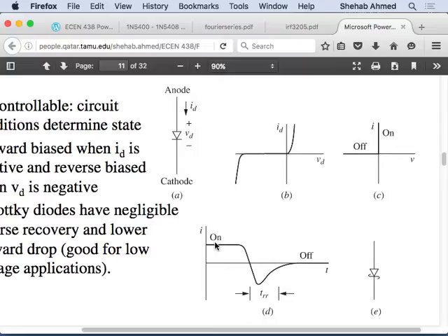So you first sketch up your circuit. Okay, this is the circuit I will use. This is how I will control it. In the control stage, I don't really care about power losses yet, because control is important. I want a range of voltage between so and so. I want a range of current between so and so. I can consider my switches as ideal during this time. And that's what we do a lot of the time.